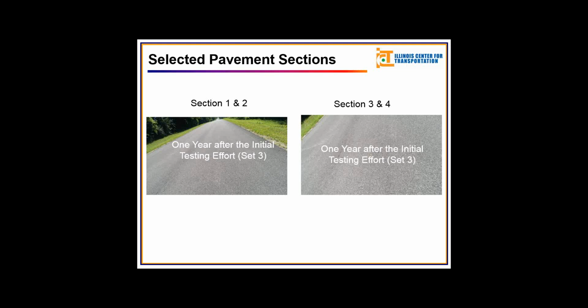And this is an implementation practice project, which is how can we actually demonstrate that even though upfront it may be a little costly, down the road this will be a better thing to do than just using the modified layer coefficient approach. Because you're totally blind in that approach by assuming layer coefficients. You don't have any means of assessing the structural condition of the existing pavement.